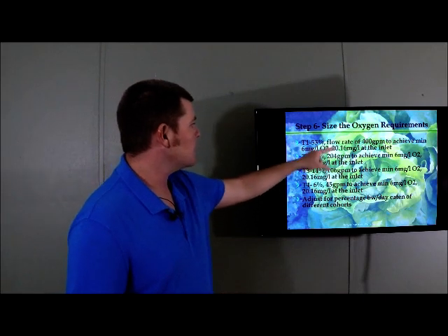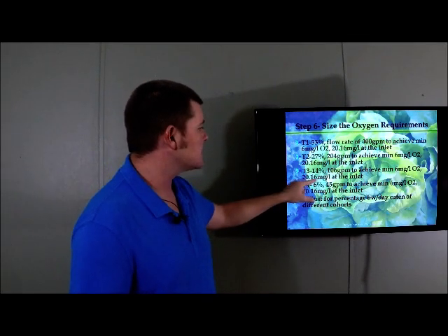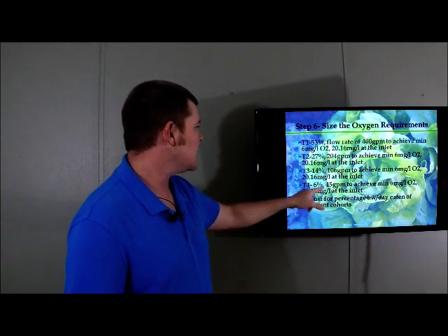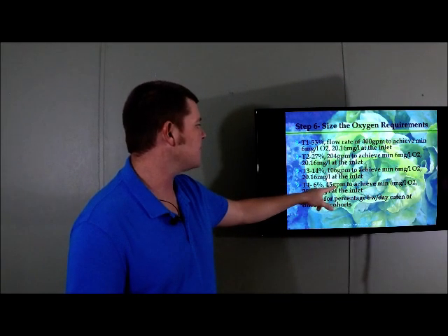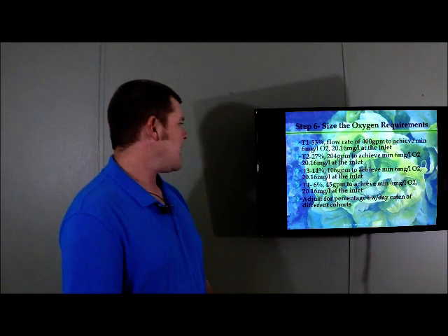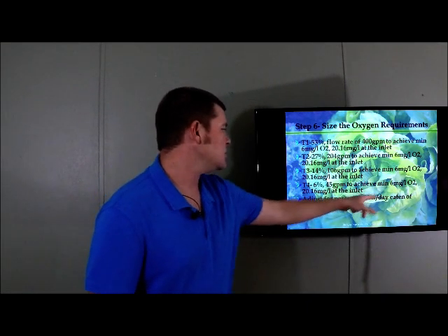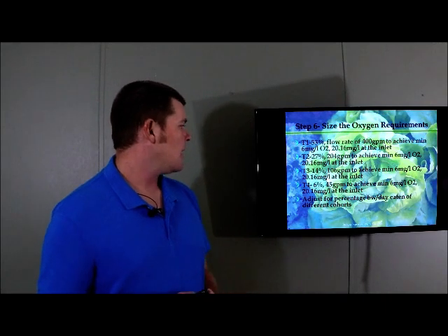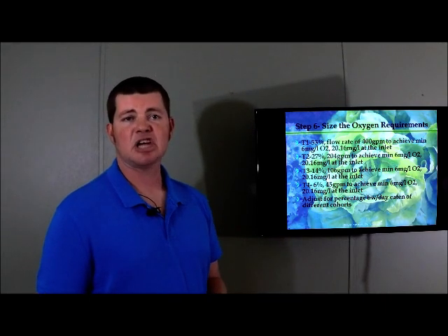Tank 3, same thing. The flow rate that we need to inject at the same amount of oxygen is 106 gallons per minute. And tank 4, the flow rate is 45 gallons per minute. Now, adjust for percentages of body weight per day eaten of the different cohorts. That's basically the adjustment you need to do.